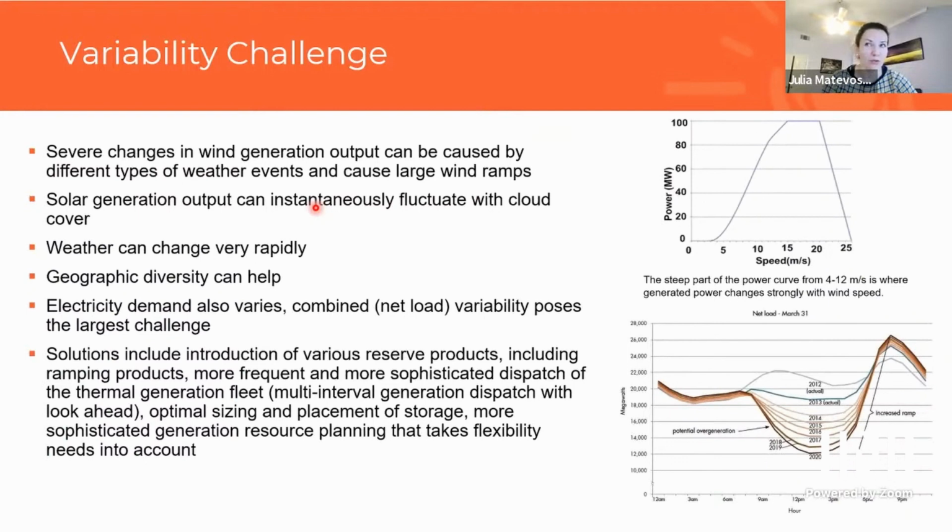And what I mean by net load is, think about the load profile that you have throughout the day, with industry and people consuming various amounts of power. And if from that you subtract instantaneous solar production and wind production, then the remaining load has to be served by other types of generation, say conventional thermal or hydro generation.